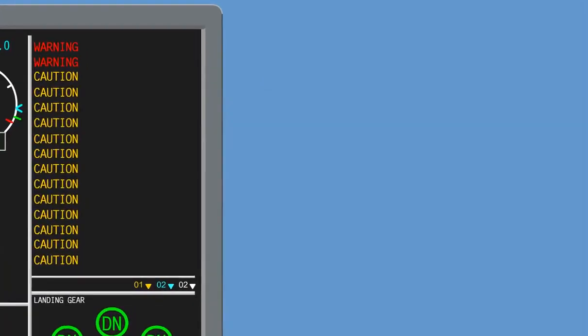The CAS field includes a status line out-of-view message display, which indicates the out-of-view ICAS messages. The purpose of this status line is to indicate the existence of undisplayed caution, advisory, or status messages, and their location relative to the currently displayed messages. The out-of-view message display includes the number of messages of each level, distinguished by a color, and an arrow indicating the direction of messages of each level, above or below the current window.